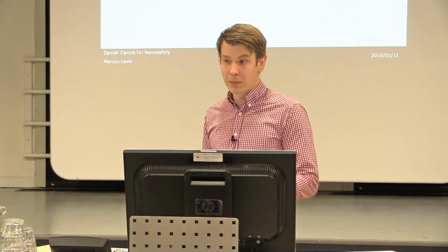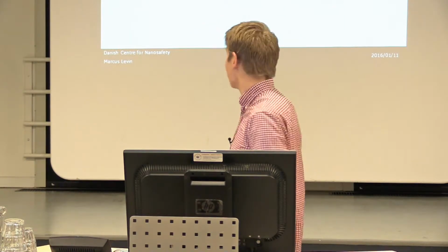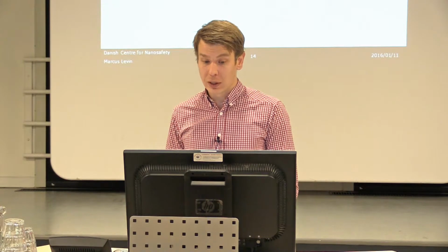And just to conclude something about this, we can see that we have some problems with the current instrumentation. We have some specific instrument problems, where we can see that some instruments are not meant to be used for this. And then we have some other instruments which are good to use for this in some cases. But we have a problem with non-sphericity, where we basically have to calibrate the instruments for the exact type of particles we want to measure. And in a lot of cases, we measure a lot of different particles at the same time, so it's not possible.